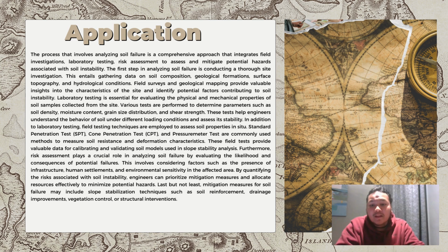Field surveys and geological mapping provide valuable insight into the characteristics of the site and identify potential factors contributing to soil instability. Laboratory testing is essential for evaluating physical and mechanical properties of soil samples collected from the site. Various tests are performed, such as standard penetration tests, cone penetration tests, and pressuremeter tests, which are commonly used methods to measure soil resistance and deformation characteristics.